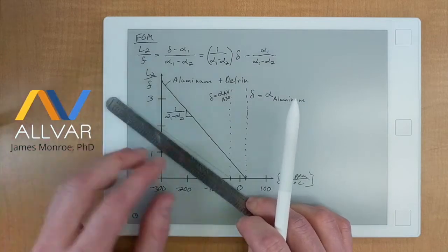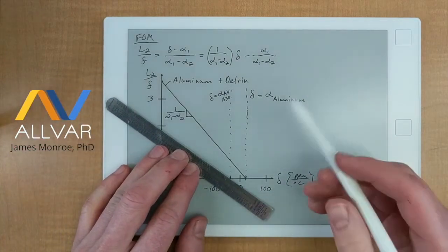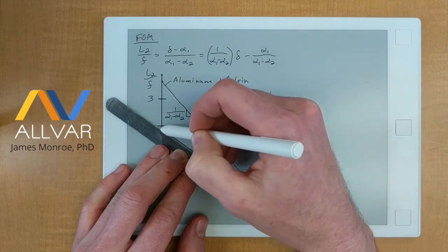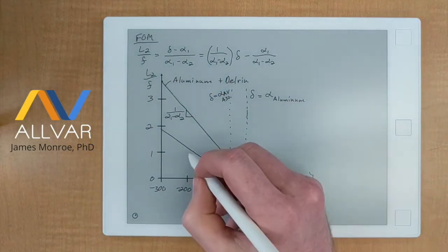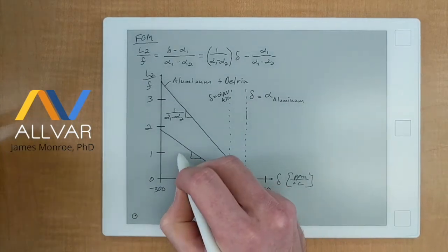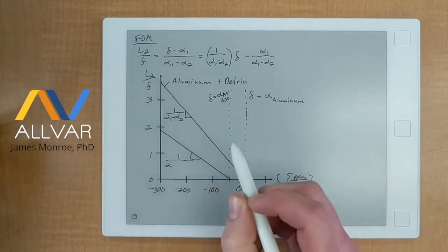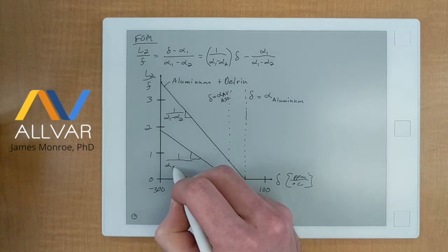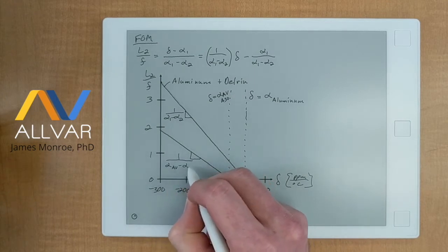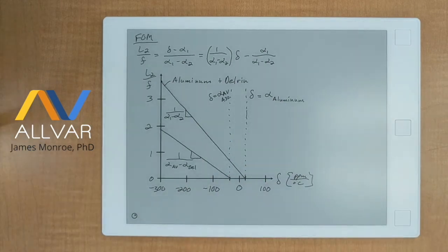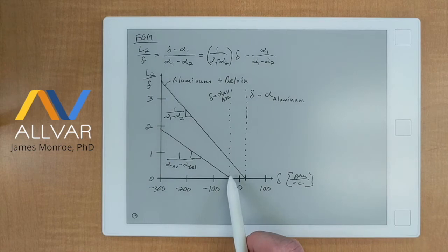So the curve starts at that negative 30 ppm per degree C, moves up kind of like that. Again, where this slope is equal to 1 over the coefficient of thermal expansion of the ALLVAR minus the coefficient of thermal expansion of the Delrin. And you also notice, in addition to the decreased slope, you also have a shifting. So you don't have to use that reentrant design for values above negative 30 ppm per degree C.